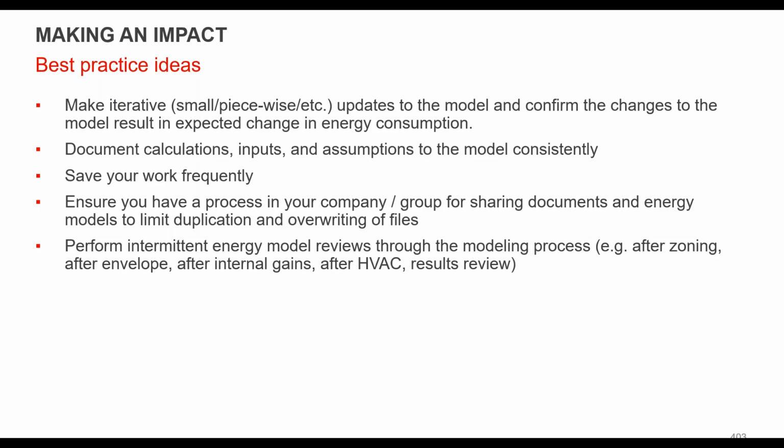Some other best practices, and these are things to take home with you, print out, think about them. Whether it's a calibrated model, a design model, or a compliance model, make small changes and run the model, and check the results, make sure they make sense, and then make another change. If you make 50 or 100 changes at one time and rerun the model and something doesn't make sense, you might not know exactly which change caused the unknown.